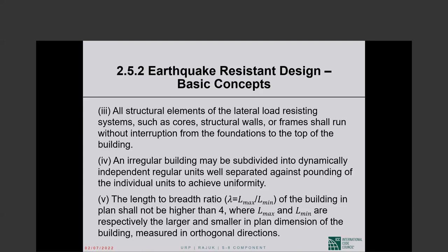And then the upper parts typically are offices, hotels, apartments, whatever. And there is no problem with having shear walls in those portions. So the shear walls in the upper portions of a building are discontinued as they come down for functional reasons, for commercial reasons. So yeah, however desirable it is, you don't always get the structural walls and frames running without interruption from the foundation to the top of the building. When they do, we are lucky. When they don't, we have to deal with that fact.